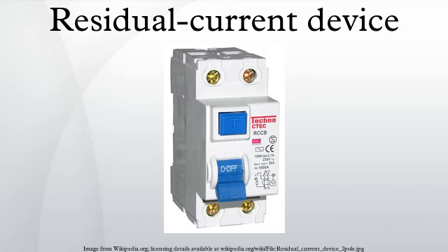In Canada and the United States, 2-wire outlets may be replaced with GFCIs to protect against electrocution, and a grounding wire does not need to be supplied to that GFCI. The outlet must be labeled as such. The GFCI manufacturers provide tags for the appropriate installation description. GFCI receptacles can be connected to also protect all the downstream receptacles on that circuit.